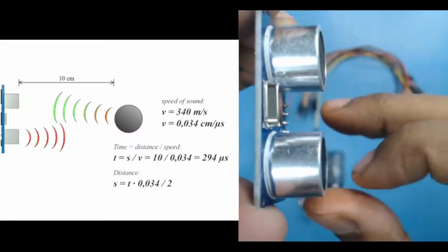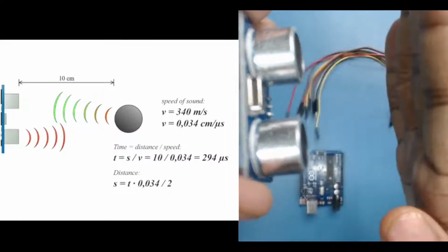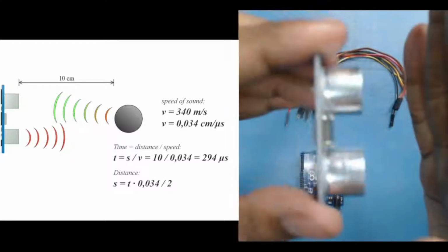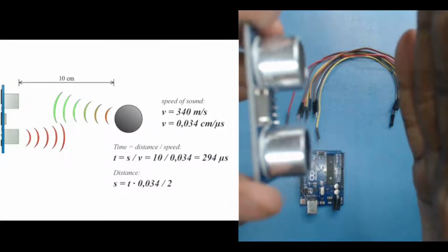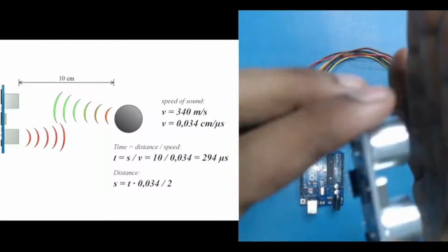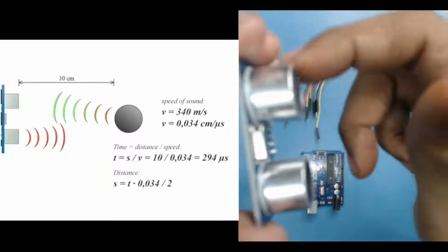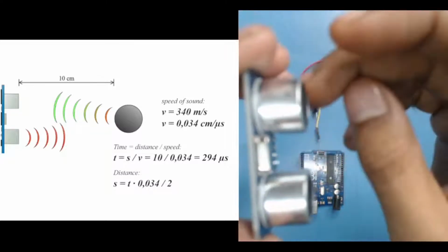So T is transmitting your ultrasonic sound waves, and because it travels through air, when an object is in front of it or comes in its path, it will strike that object and reflect back, and the reflected waves are received by the receiver.